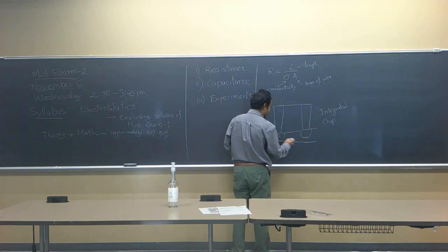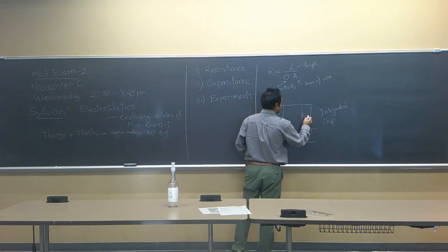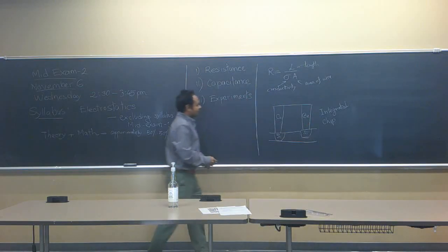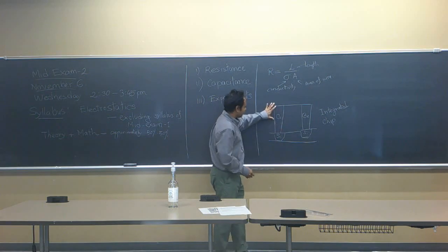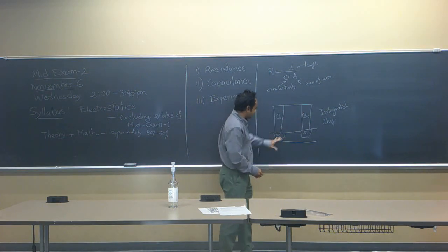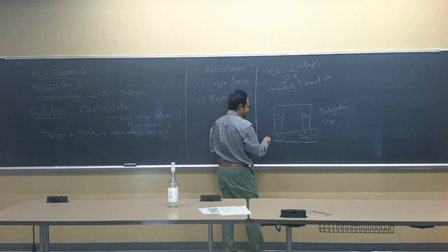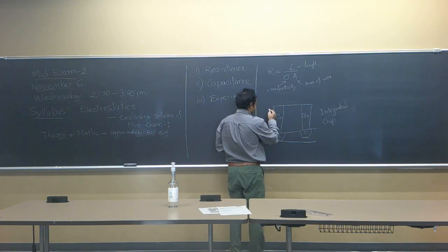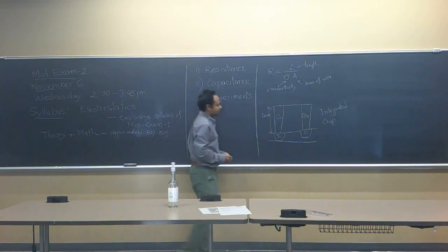So these are all silicon devices. And on top of the silicon device, we make wire by depositing copper metal. So these are copper metals on top of silicon, and these are the silicon devices that will act as a transistor. The typical size of a copper pillar is in the order of micrometers.